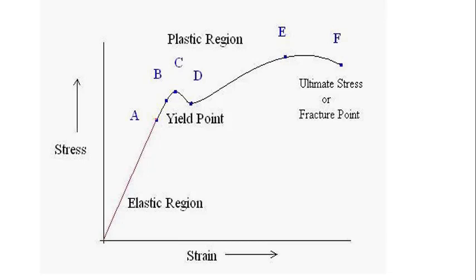We can get this stress strain curve from the universal testing machine by performing a tensile test on the given object. This is the stress strain diagram for mild steel. If we apply a load on an object, this is the reaction of stress and strain. We can plot a diagram on that.